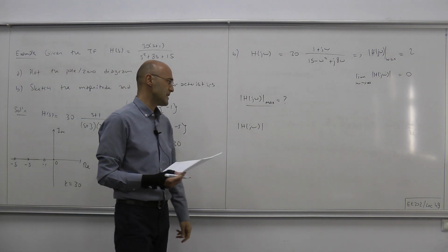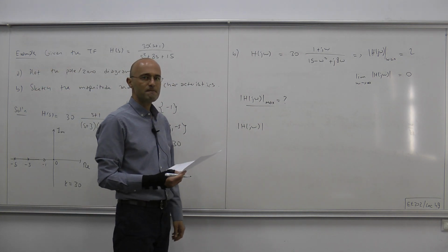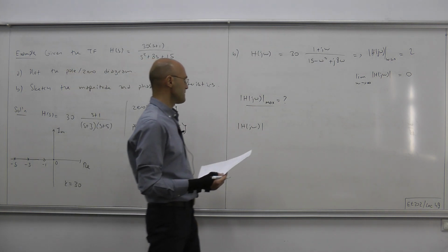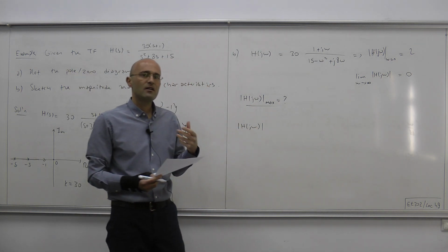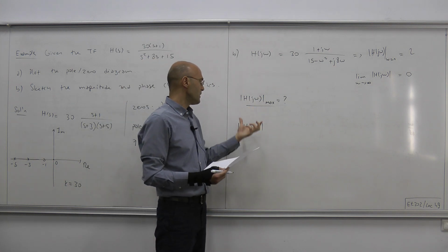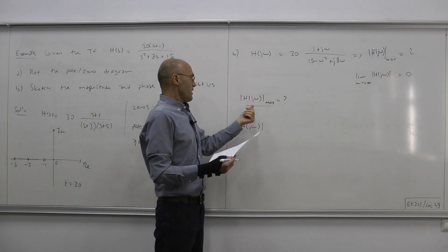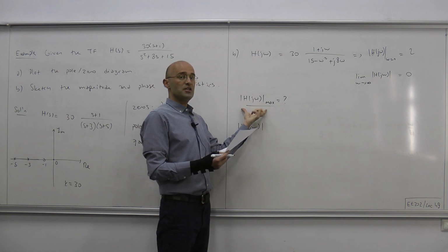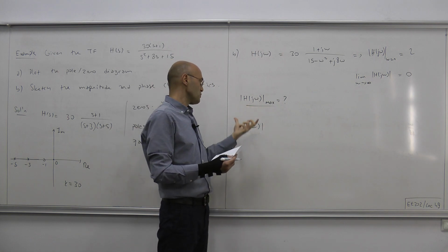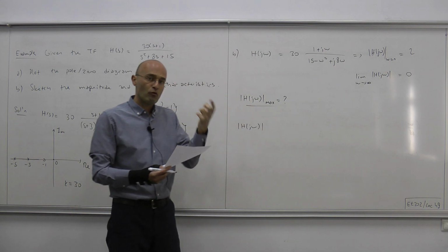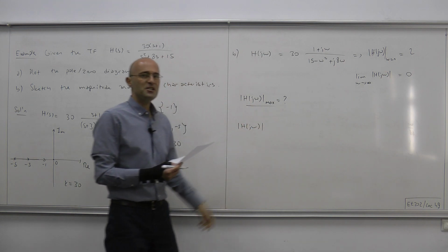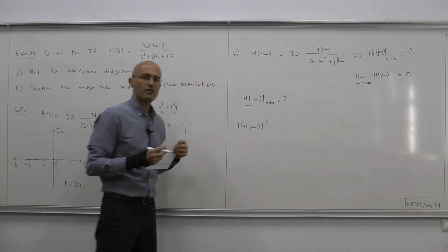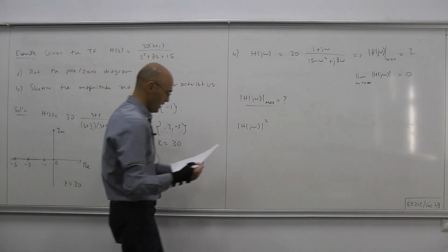that value is attained. Now, since we're going to differentiate to find the extremum point, it's better to work with the square of the gain instead of the gain, and note that whatever frequency the maximum value is attained at should also be the frequency for which the square of the gain is maximum. So to figure out that frequency, we can work with the square of the gain.